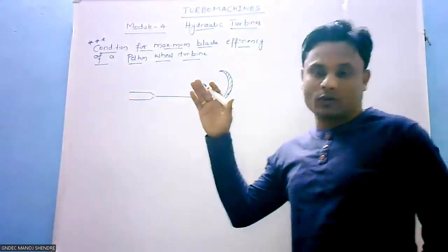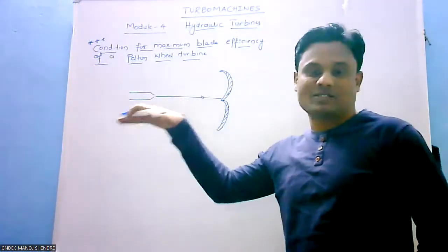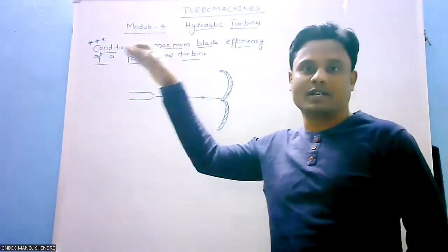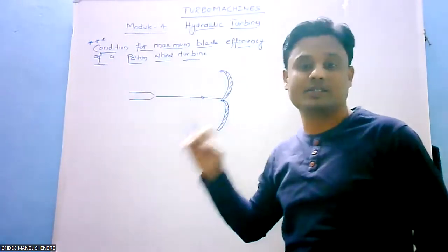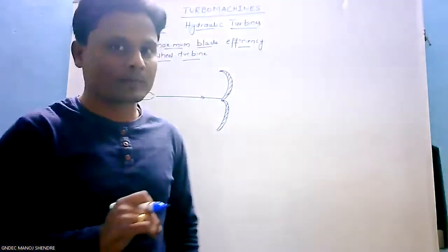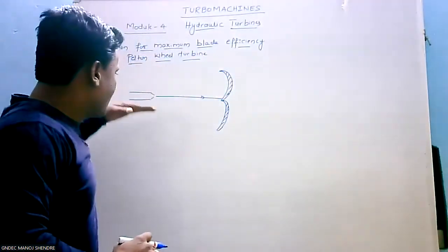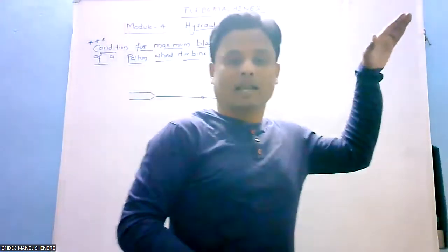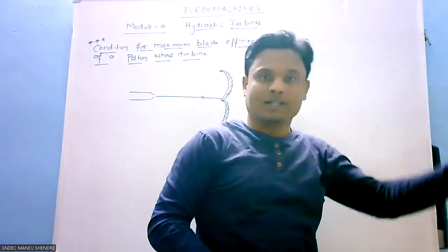As we know, the nozzle is horizontal, so that's why the inlet velocity triangle collapses to a straight line. This is a very important point in the derivation that you need to keep in mind. I'll repeat it once again: as the nozzle is horizontal, the inlet velocity triangle collapses to a straight line.